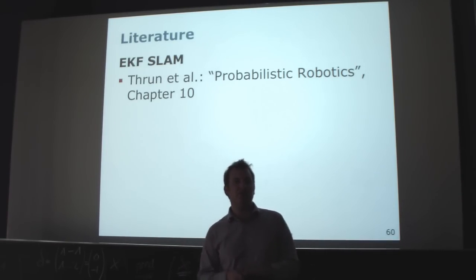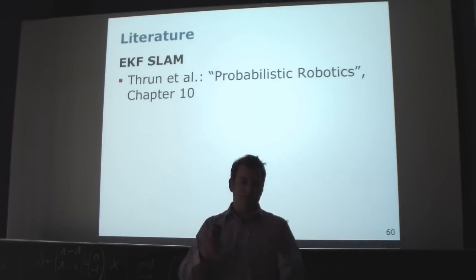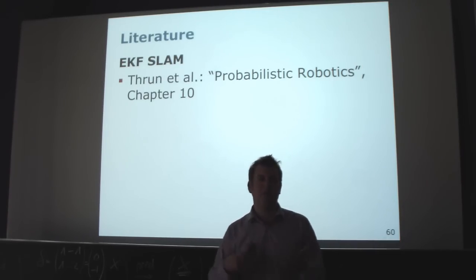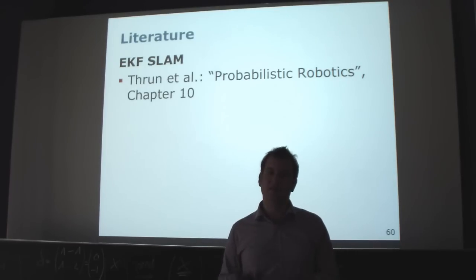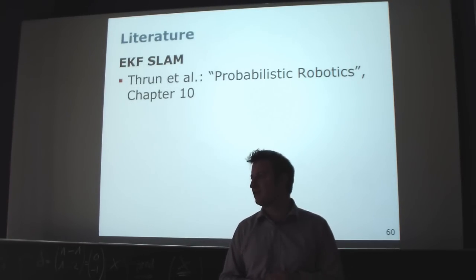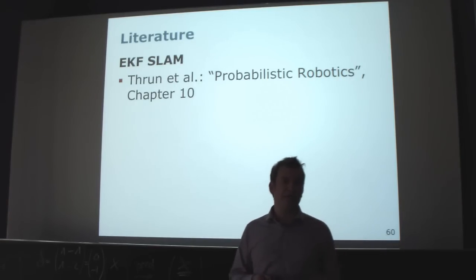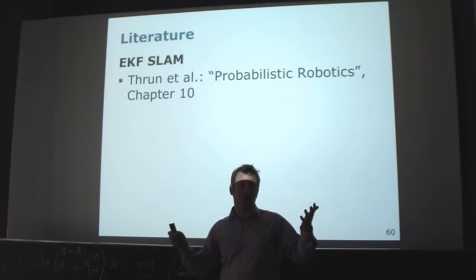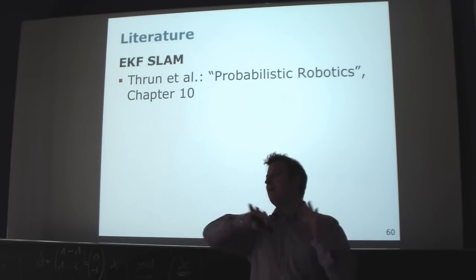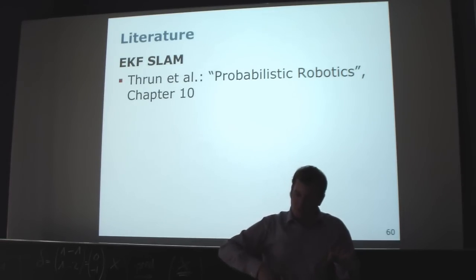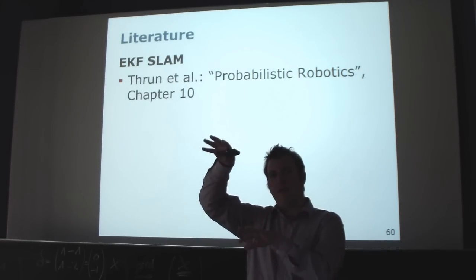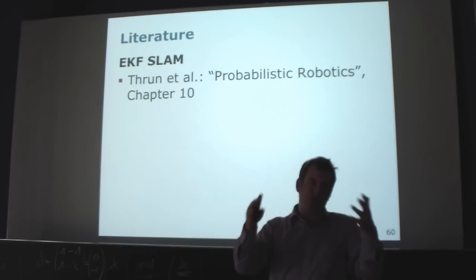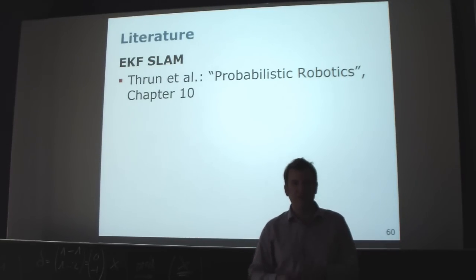If you have further sensor information, like visual information which can provide SIFT features, SURF features, whatever features about the environment, or some other technique for place recognition, you can perform much better than this kind of stupid, straightforward nearest neighbor association. But this depends on the application. Beyond doing nearest neighbor associations individually, you can also use solutions to assignment problems when you observe multiple landmarks. As you drive a bit in the environment, you build local maps and do the data association a little delayed, fixing it only if whole submaps correspond to what I've seen before. There are certain tricks like delayed data association which improve the situation, but still.